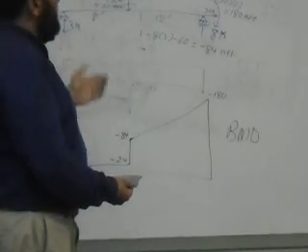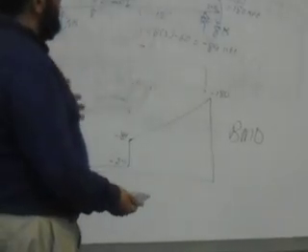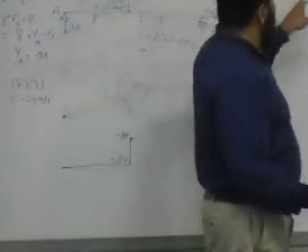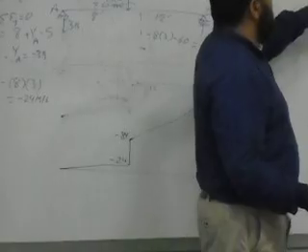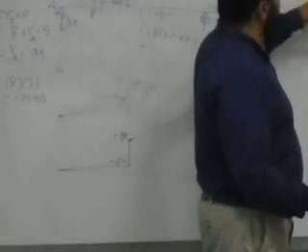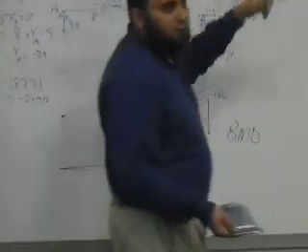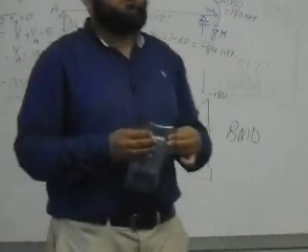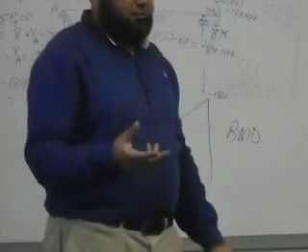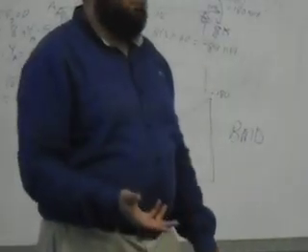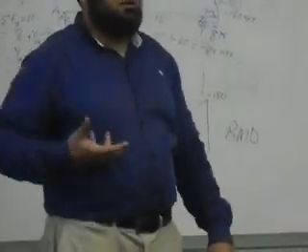However, for a simply supported beam, like this one, you will have the main reinforcement in the mid span down. At the supports, there will be negative moments, so the steel will be up. So it helps you understand at the design stage where you will place the reinforcement. But this is why in Egypt we focus a lot on this issue.